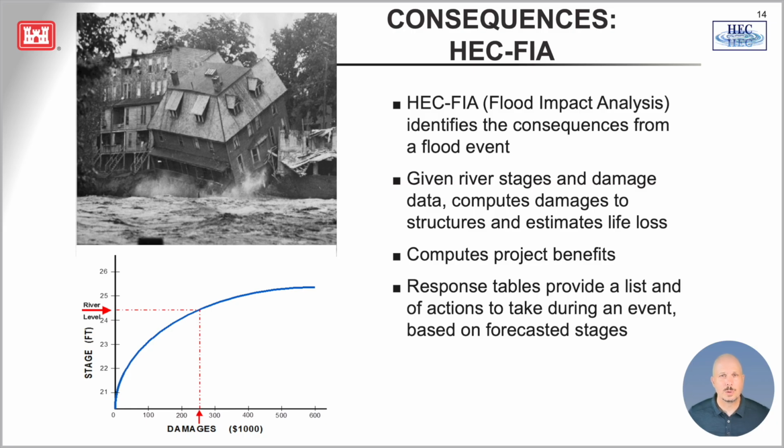Finally, the full suite of SWMS models, including HEC-FIA, are also used on an annual basis to conduct flood damages reduced, FDR, analyses for all flooding events that transpire in a year. These analyses estimate the cumulative benefits of core reservoir operations in mitigating flood damage costs based on the simulation of regulated conditions versus unregulated conditions.